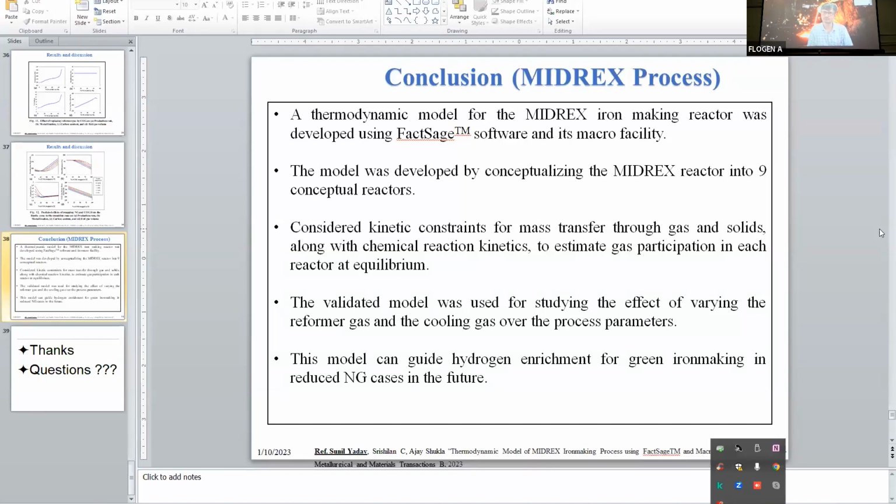We need limestone much more, and the slag is not good to use, very harmful in comparison to the blast furnace slag. That's a byproduct for blast furnace cement. So that's the point. Even the Brazilian iron ore, very high grade. In Japan, the low grade iron ore we often use, but in both cases, there is a gangue mineral. So how can we overcome the slag in the steelmaking stage? We can't use the harmful slag. Do you have any idea to overcome this problem?